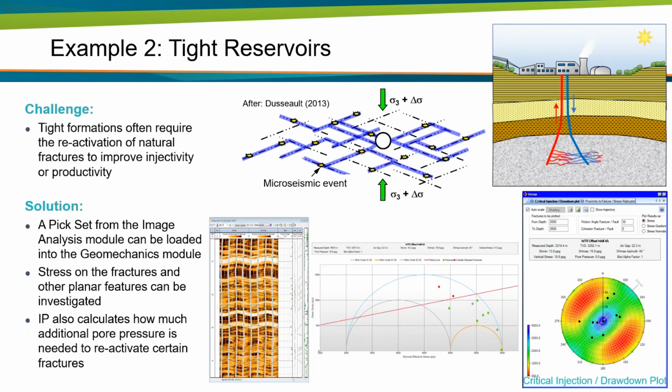So we do that by injecting low viscosity fluid, typically simple water, into the wellbore, and that fluid increases the pore pressure in the formation. It goes into these natural fractures and reactivates them, and so we get microseismic events, which are kind of proof that we are actually reactivating these fractures. And when these fractures reactivate, they go from this state to a reactivated state.